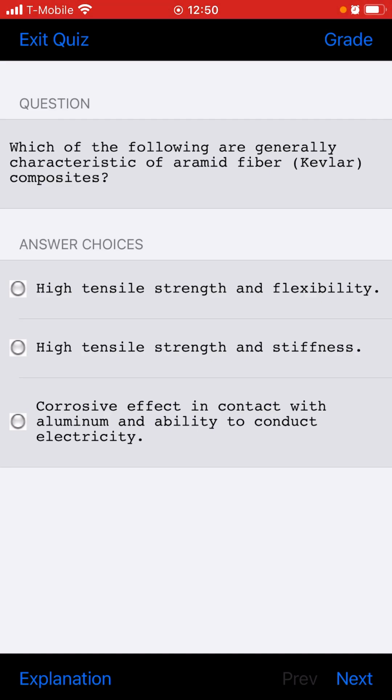The length of a rivet to be used to join a sheet of 0.032 inch and 0.064 inch aluminum alloy should be equal to 1.5 times the rivet diameter plus 0.096 inch.